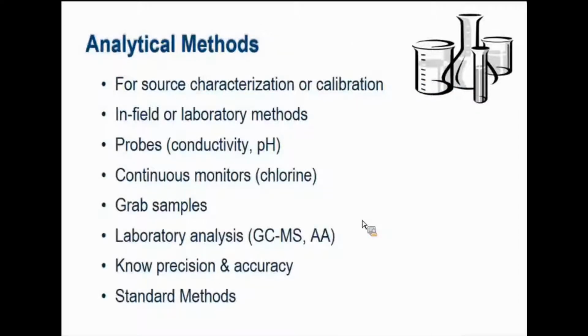Calibrate your equipment. Anything that you're using in the lab, make sure you calibrate it, follow lab procedures, because whatever values you're getting out of the laboratory results here, you're going to apply to the whole model. So it's going to have a direct effect on your results. And so the quality, or whether or not you need to repeat the test to improve the confidence of the values that you get, you might need to do that as well.